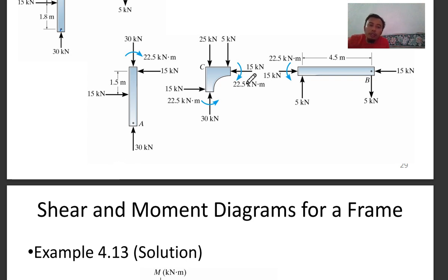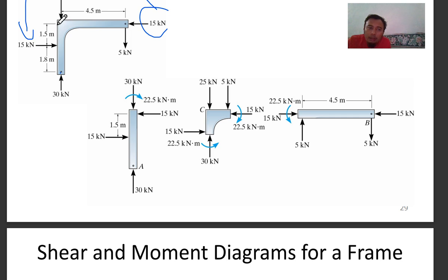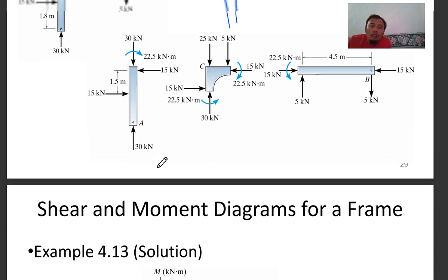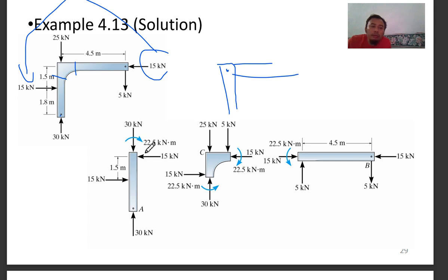At the angle here there is a fixed joint. It's fixed when you cut here. Sometimes you get a combination with a pin. When there is a pin, you can resolve it, and you don't have any bending moment, right? For that, like this example. So when you cut into sections, you can solve the reactions.